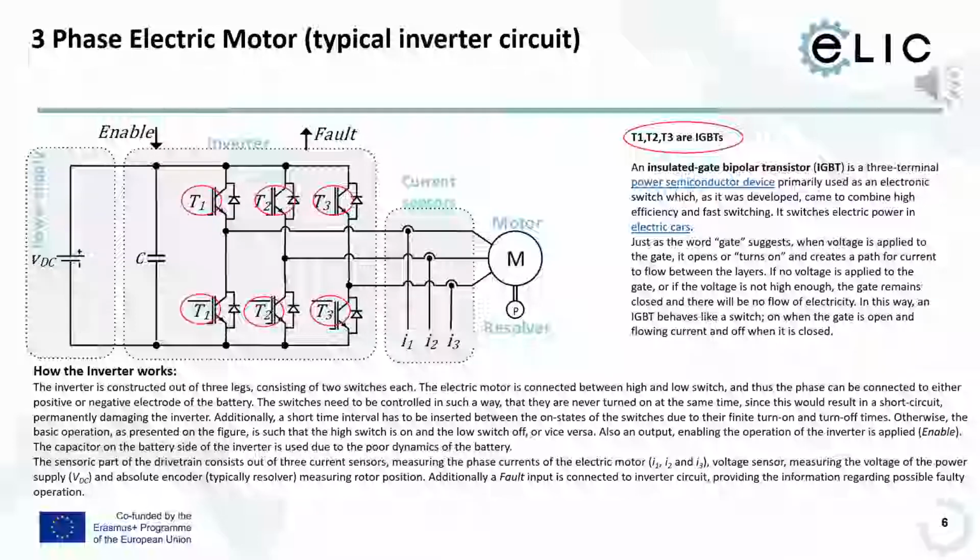And the FOC, which we have heard before, which is this software component, is the algorithm or contains the algorithm that controls when we switch to the high or low switch in a clocked way to control the e-motor. Basically, we always switch between high and low switch, and in the next slide we will explain why that is needed.